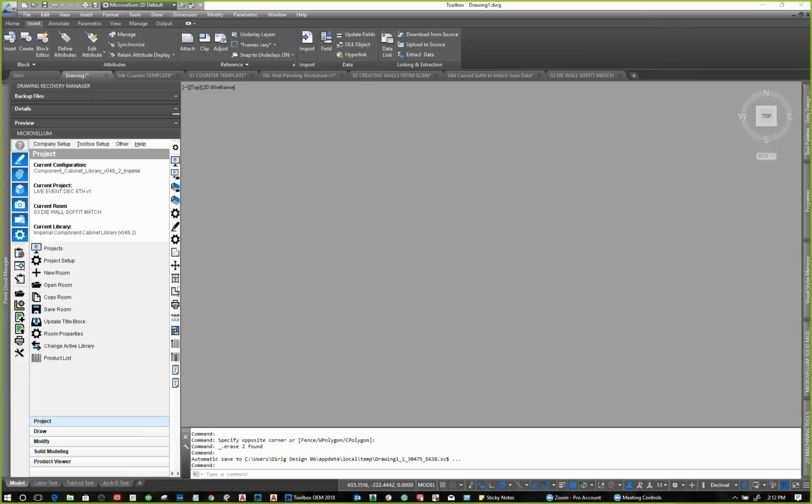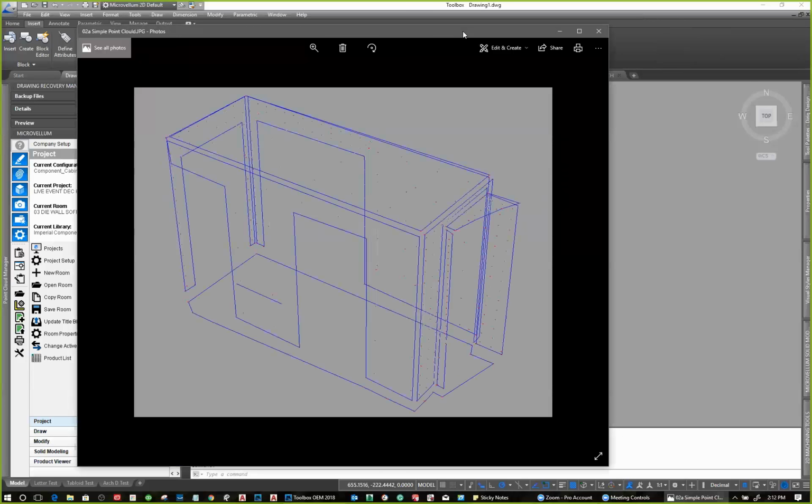So typically with the 3D Disto, when you go out and you measure, this was a room I measured a few weeks ago in a penthouse in New York, and we were doing wall paneling. I was able to just capture, I think it was about 230 points on all the walls and the ceiling and the floor. And then when I brought this back into CAD, I'm able to tell if the walls are out of plumb, if the floor is not level, if the ceiling's not level. And really all that I needed was this. So when I walked away, I was able to bring this right into CAD and then start working from that.